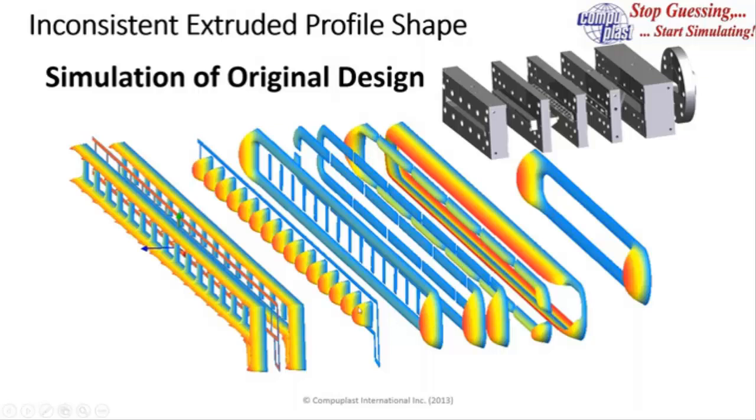And the next cross-section, now in order to get the flow into the ribs, they make those channels very large, so you get large high flow in the rib sections, but very low flow on all the outside channels. And then the channels that they eventually tuned at the exit seem to be fairly well balanced in terms of overall flow and how much material you want.